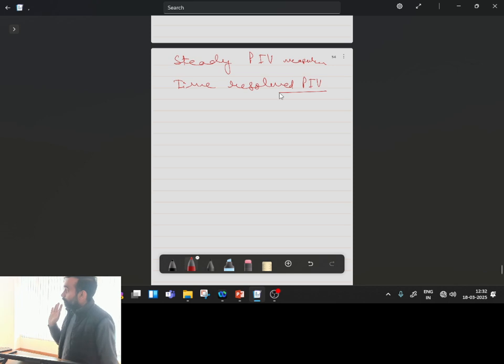But if I go for a turbulent flow situation, in case of highly turbulent flow, what will be happening? Because the flow will not be steady and smooth, whatever care you take in deciding the plane, there will always be some component of velocity perpendicular to the plane, leading to motion of particles in the transverse direction.